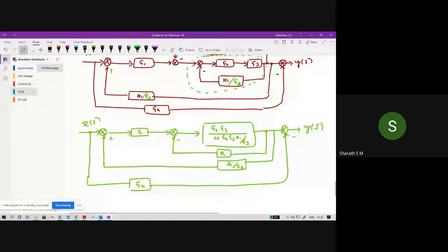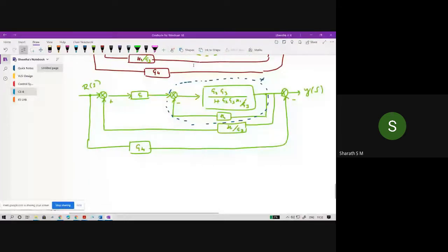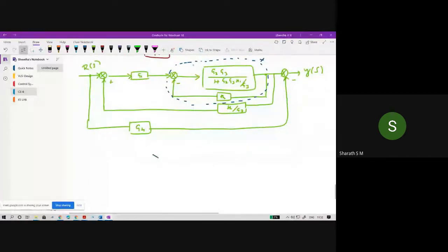Afterwards, for this H2, write down the negative feedback equation for this particular loop. And then these two are in series, and then write down the positive feedback equation for this. I'm going to choose this as a temporary variable X. So X into G1 divided by 1 plus x into h2.